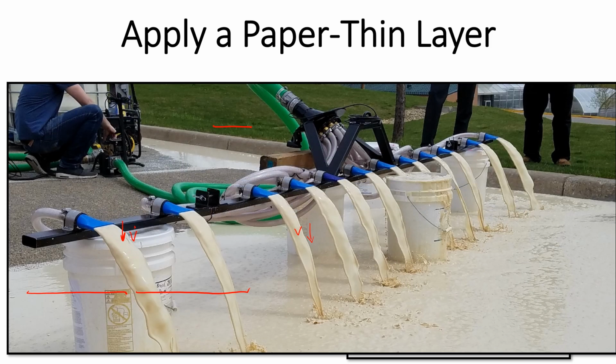This then is a depiction of the assembled full-scale model, showing the distribution manifold, wherein the Zequanox water mixture is pumped in through this 3-inch diameter hose, and then distributed among smaller hoses to the 12 injection nozzles shown there.